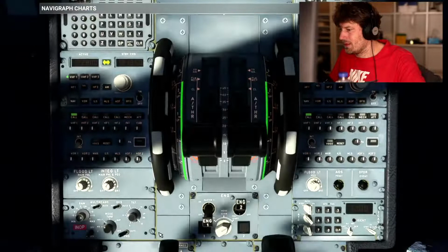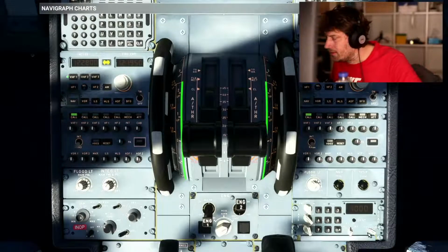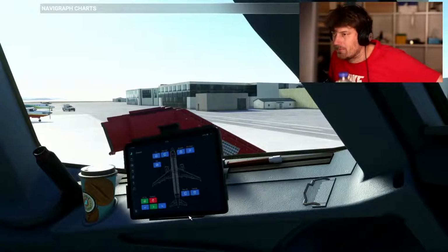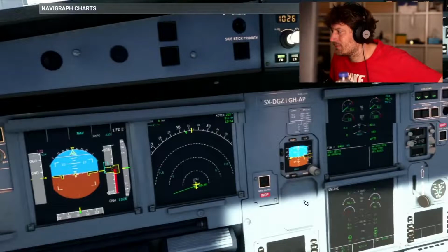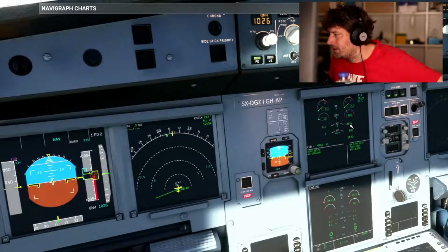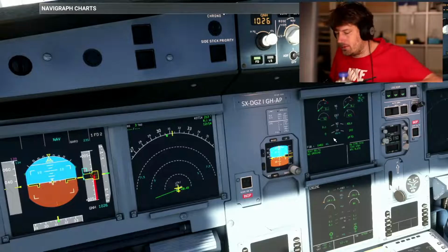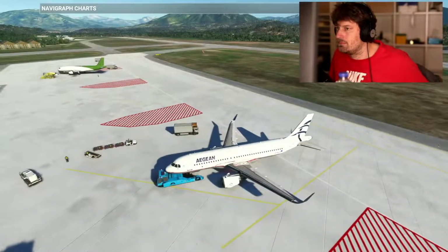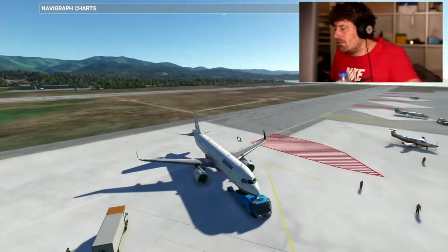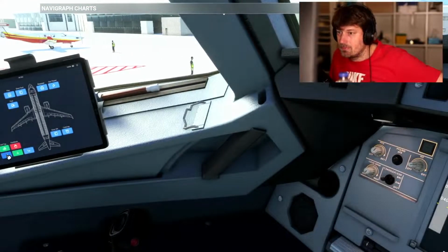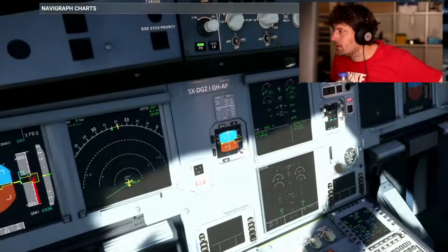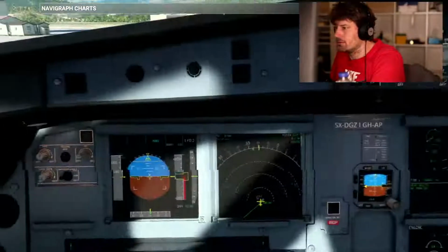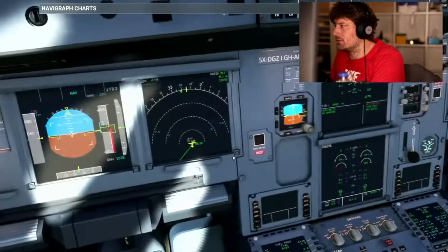In the meantime, we can release the parking brake and request our pushback. We see that fuel flow is there, N2 is increasing, EGT is increasing, the N1 is also increasing. And 15%. This is available. We can start engine number 1 now.